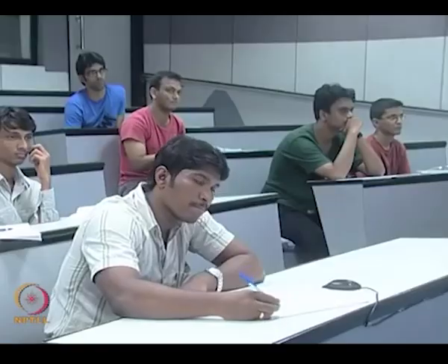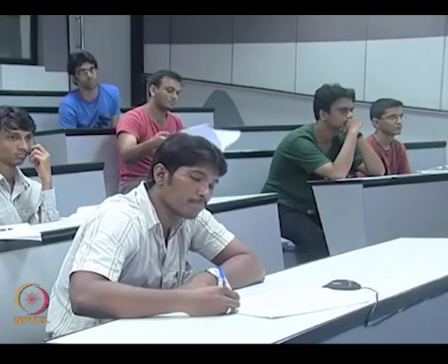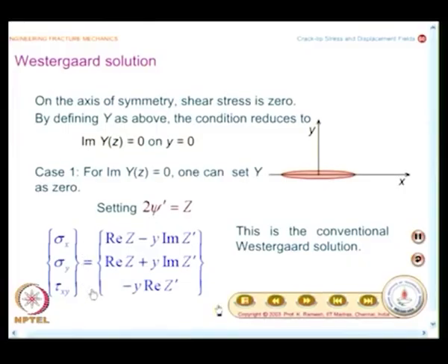So, you have to exclude that inelastic deformation zone, and you have to live in that singularity dominated zone. I had already mentioned the size and shape of the singularity dominated zone is problem dependent, but you will have to have a concept of in what way this equation could be valid from an experimental point of view: you are able to collect data only in a very small zone close to the crack tip.